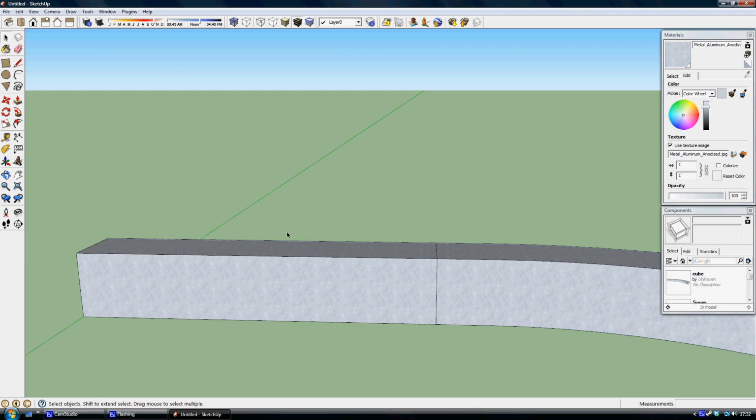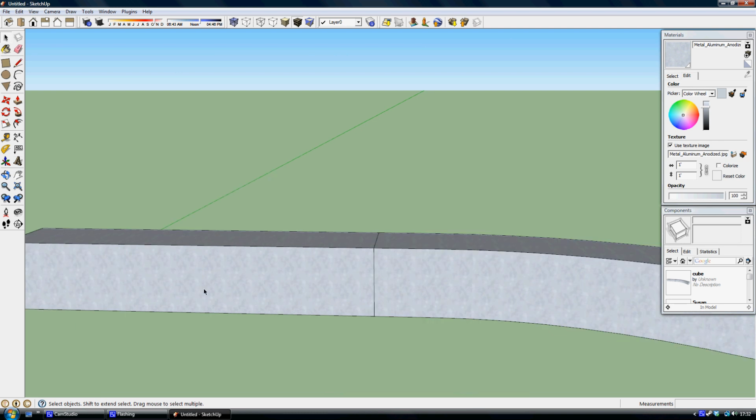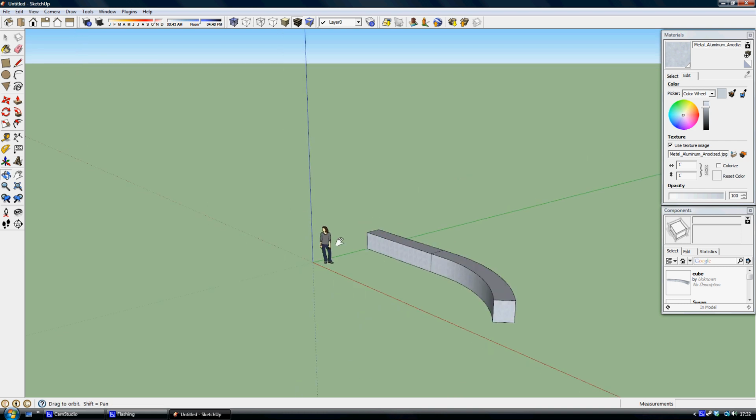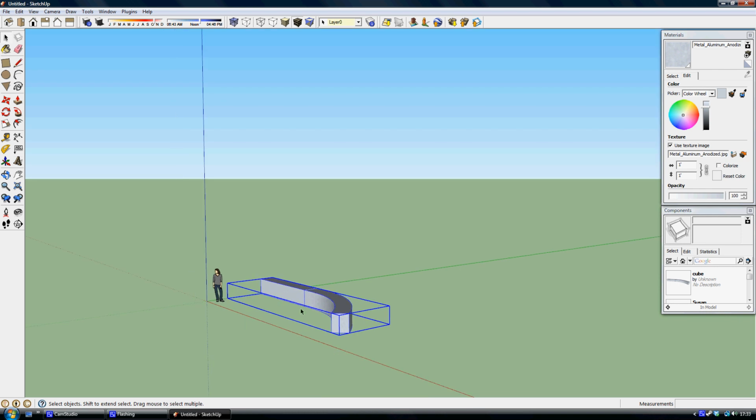And they just come in really handy if you've got a very big mesh, because in Sketchup, if you overlap lines, it will then merge onto the other model. So like I showed you earlier, this face got divided, but with a component that wouldn't happen, and it just makes things a lot easier to edit. Say if you had a full house and you had the downstairs walls, upstairs walls, floors, furniture. For a game engine, you'd obviously want all those objects separate, so that's where components come in very handy. You can select one, export that, save it as a different file, and it just makes editing a lot easier. I hope I've explained that well enough.